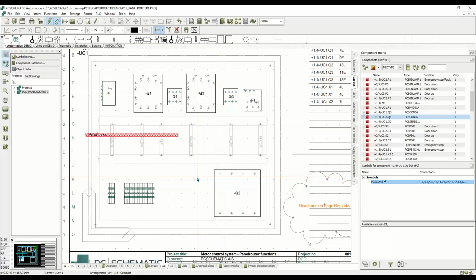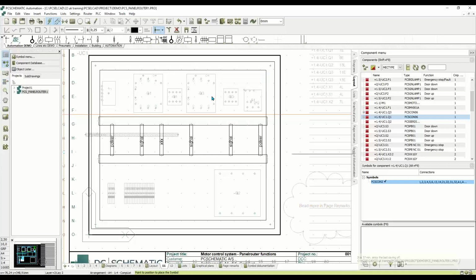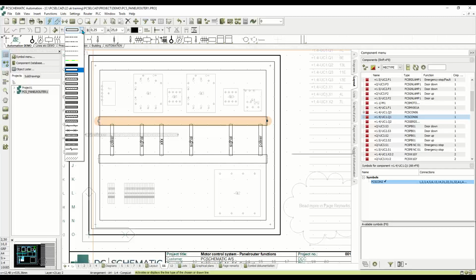And the thing is that when I have a panel and I use it as a symbol, if I click anywhere on the symbol, I might select the panel and then everything will move. So that's the reason why I put the panel and the trace in one layer, and the normal components in another layer. And I simply use the layer function to do that. And then again, those wire trays here, I'll just go up here, they are this type of line, this not filled out but empty frame here. That's the type that I use for my wire trays.